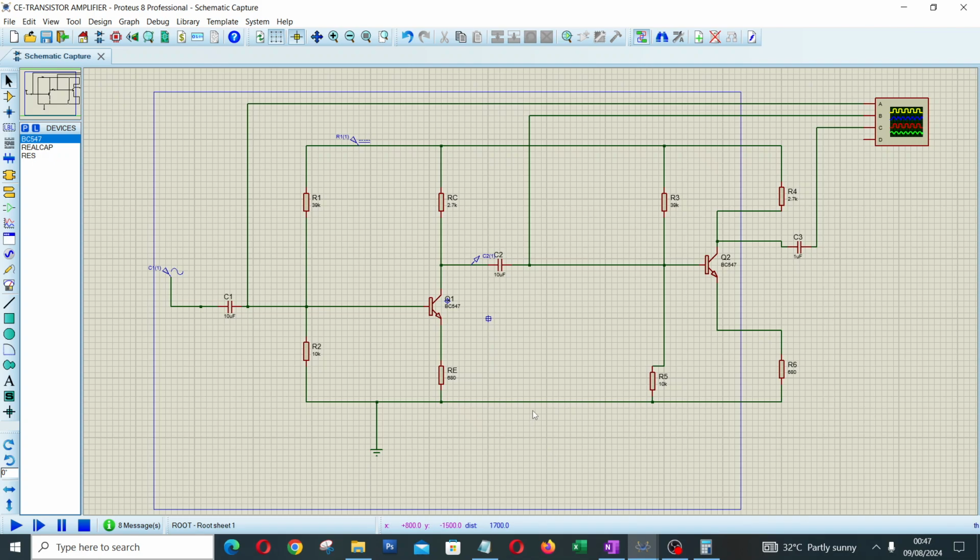If you have been following us all this while, you will find out this is the circuit we worked on the other time. We took ourselves through how we arrived at these particular values for these biasing resistors. Remember, I did mention that this type of biasing is called potential divider biasing method, and we took ourselves through how we calculate the values of R1, R2, RC, and RE.